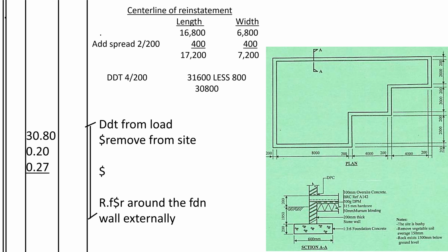of reinstatement, whereby we take the centerline of the spread here, because the spread is up to here, 200. Now this one we shall come at the center of this spread. So you need to find the external dimensions of the spread. Remember, external dimensions of the spread. Then we deduct the number of corners times the thickness of that spread alone. So what guides you is this one.